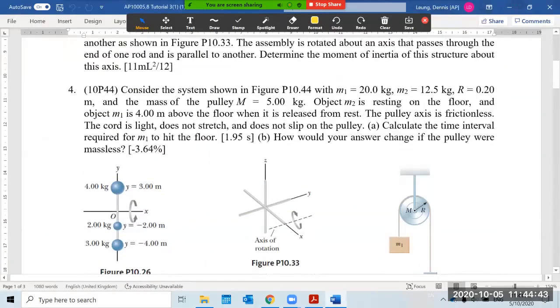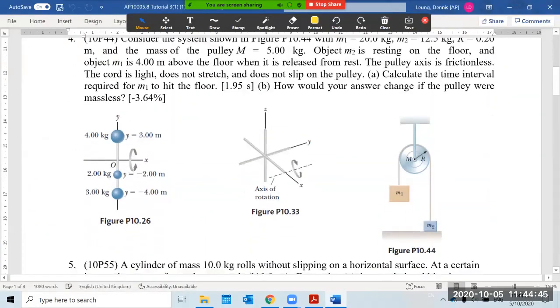So tutorial question 4, we have seen this example, which is a three-dimensional cross, if you like. The axis of rotation is not through the center of mass, but at a distance L/2 from one of the axes. So to make the calculation simple, we could firstly calculate the moment of inertia about the y-axis, which is going through the center of mass for the whole structure.